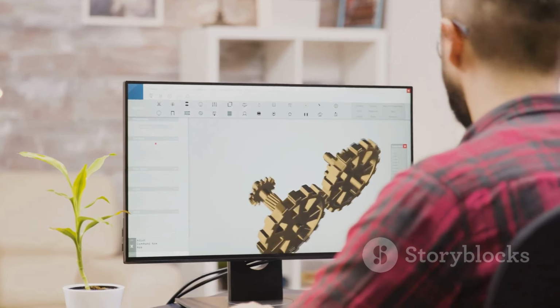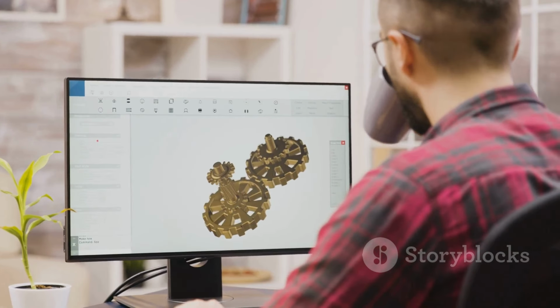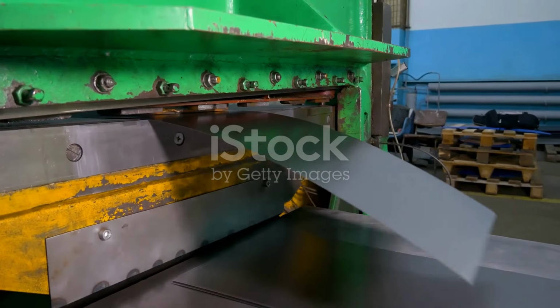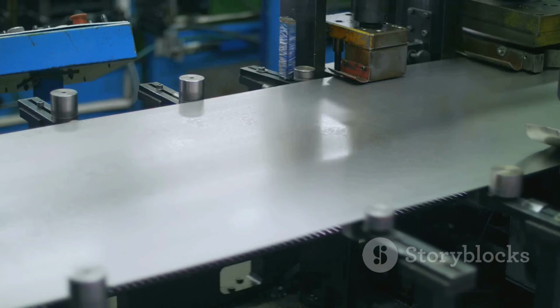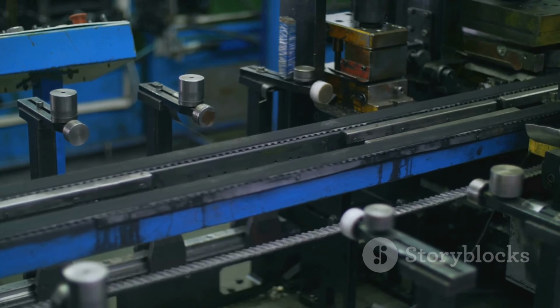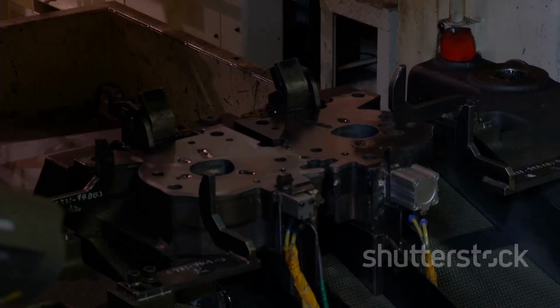Section 7. From screen to reality: building a sheet metal box in SolidWorks. Let's put our newfound sheet metal knowledge to the test and build a simple box in SolidWorks. This practical example will walk us through the entire process, from creating the base flange to unfolding the final flat pattern. Start by creating a new sheet metal part file and defining the base flange.